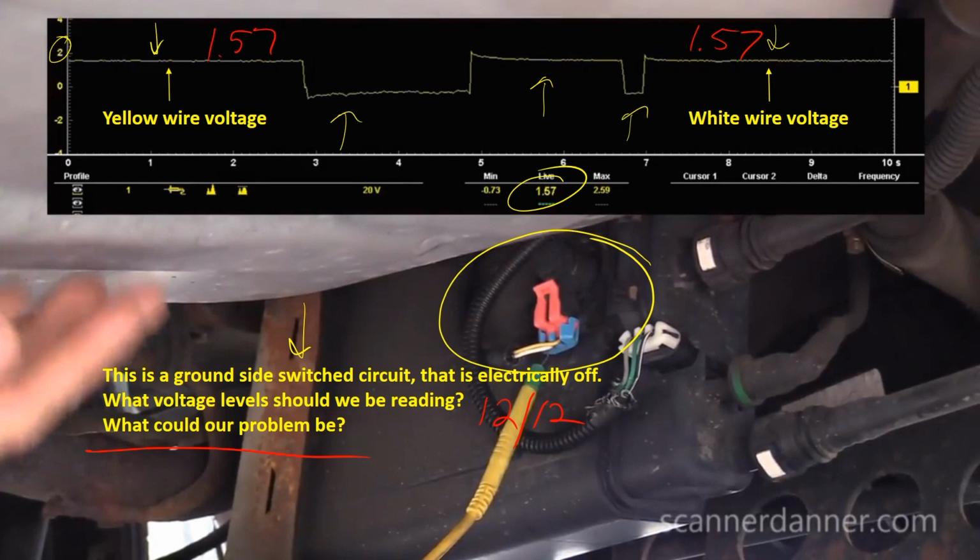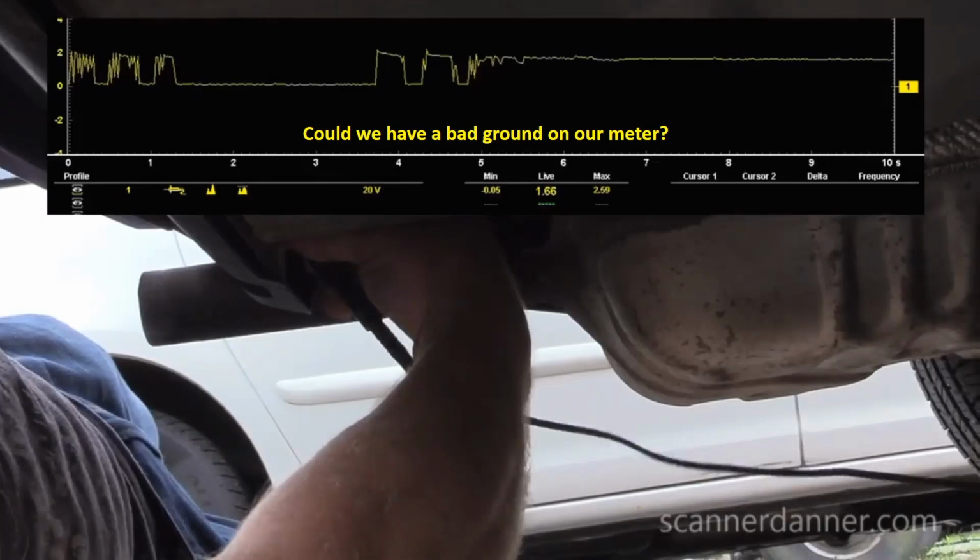Because if my meter has a bad ground, then these voltage numbers I'm getting here are skewed and I can't trust them. So in the next capture, that's what I'm doing. In the video, I'm moving my ground because I'm in the back of the car. What I like to do typically is wherever I'm taking a measurement, I'll put my ground for my meter.